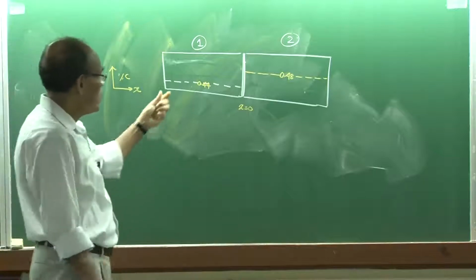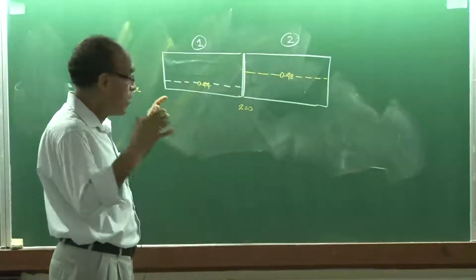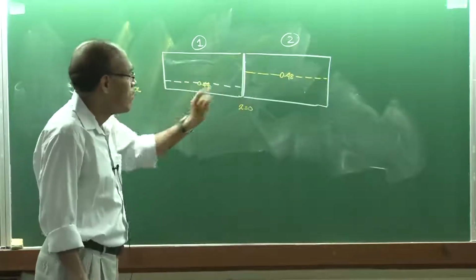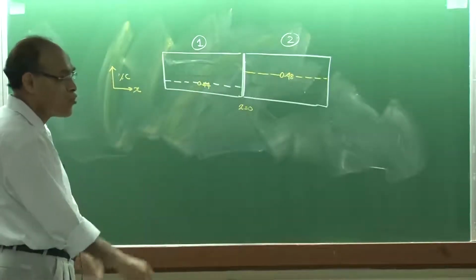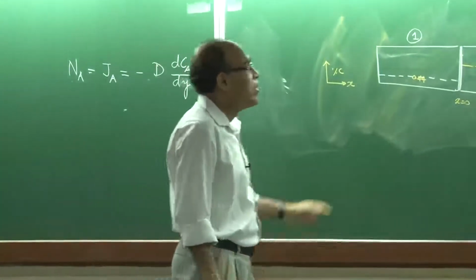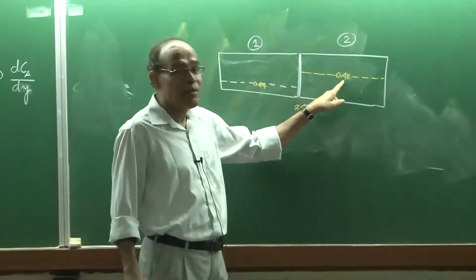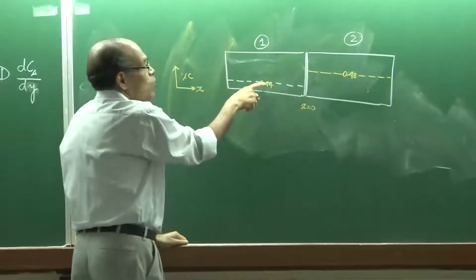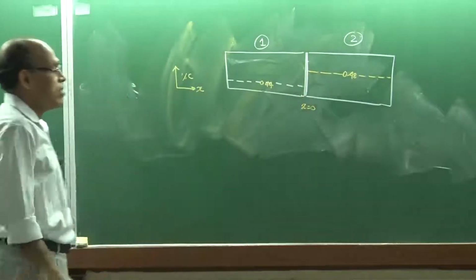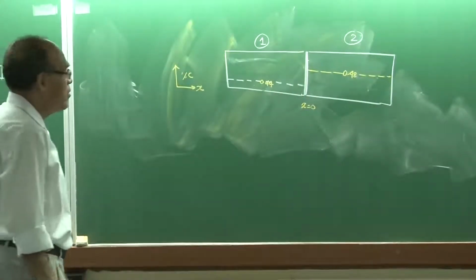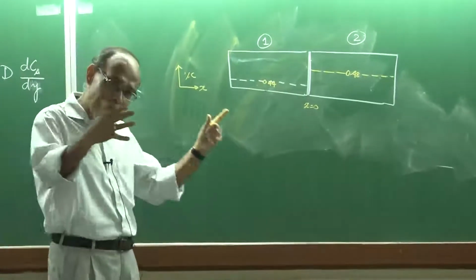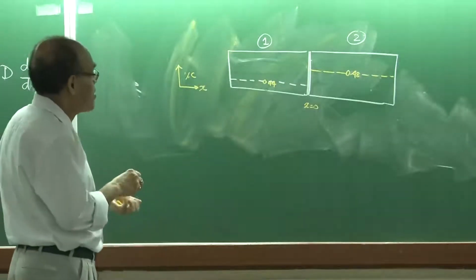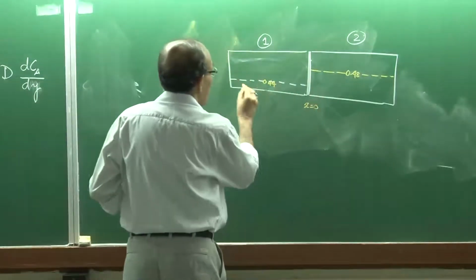At high temperature, when they are at the same temperature and you want to maintain it isothermal, that is the experiment. So under isothermal condition at a high temperature, when both of them have equal temperature, and these two materials are joined, as far as Fick's law, as I have written here, it will suggest that from a region of 0.48% carbon, material will flow to 0.44, because this has higher carbon concentration and this has lower carbon concentration, so the material will try to flow in this direction. But what Darken saw, after 13 days of keeping the diffusion couple in contact, and then separating them and looking at the microstructure, very interestingly, he found that the graph has become something like this.